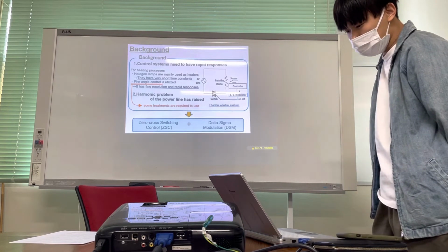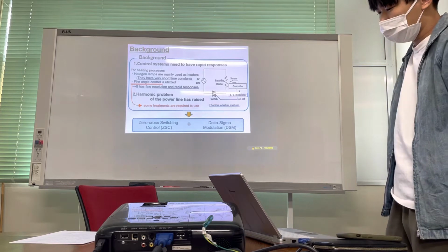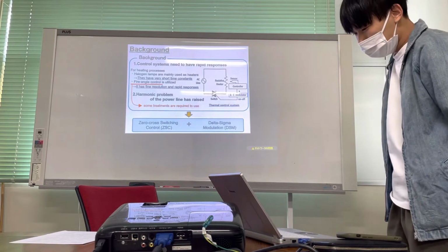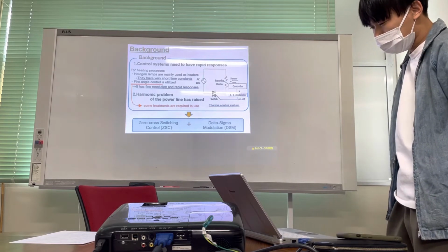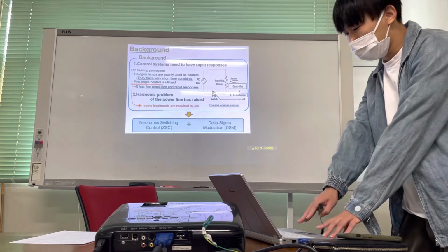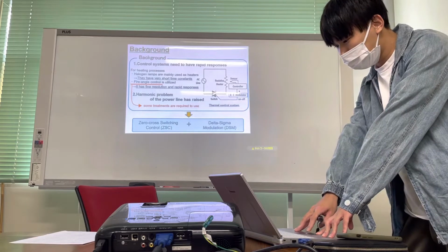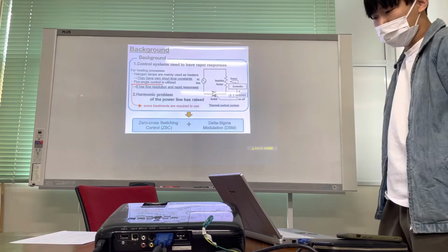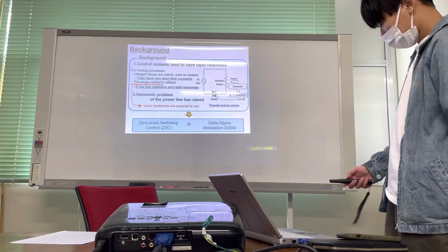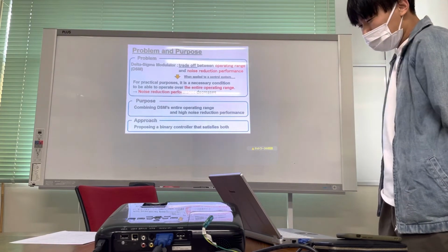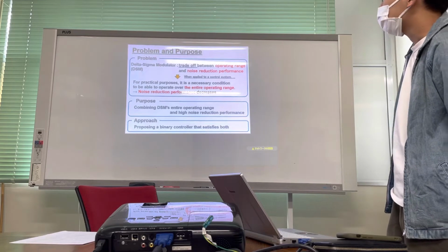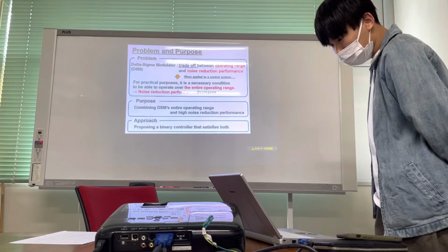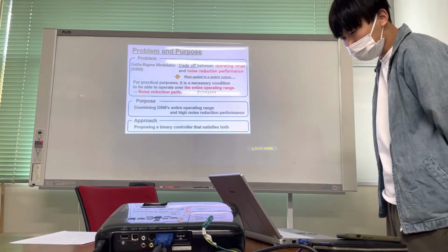Zero-cross control is a method of switching on and off when the AC voltage becomes zero. Using this method, precise adjustment can be performed with much fewer harmonic components of the consuming current. Next, I explain how to combine the zero-cross control and delta sigma modulation.